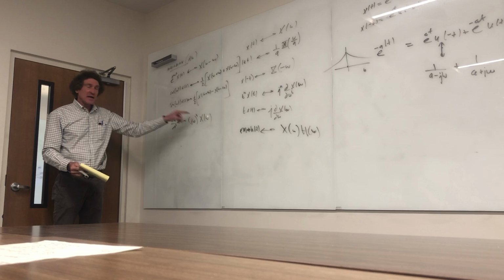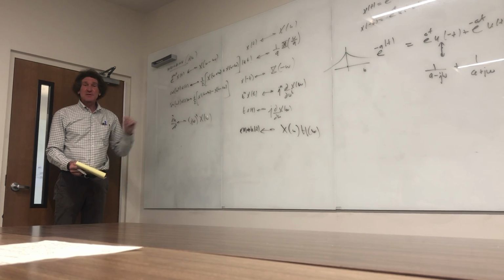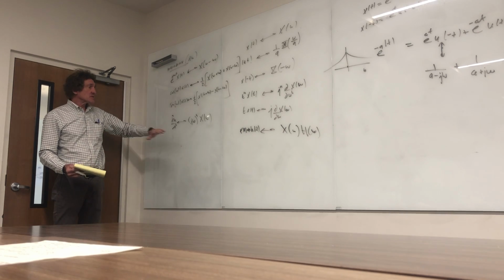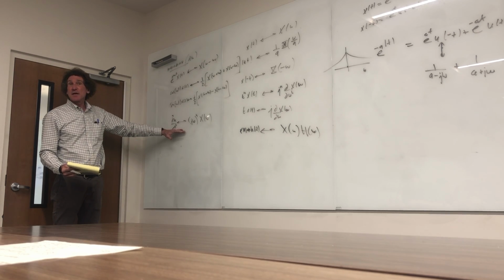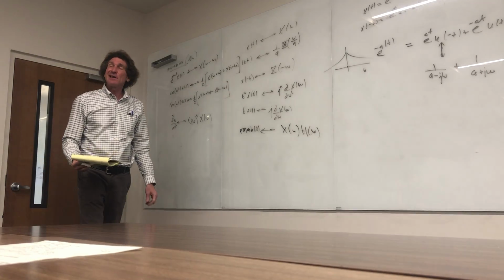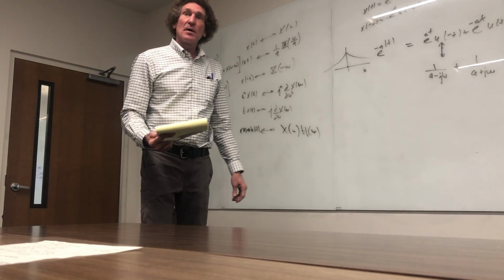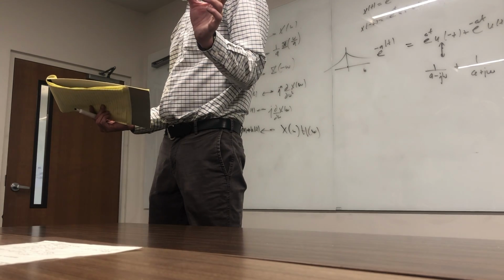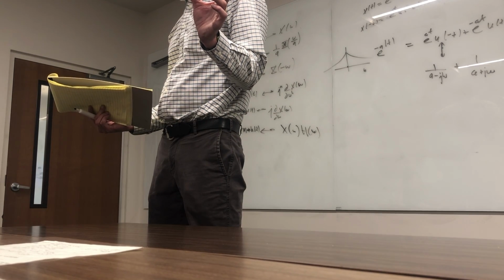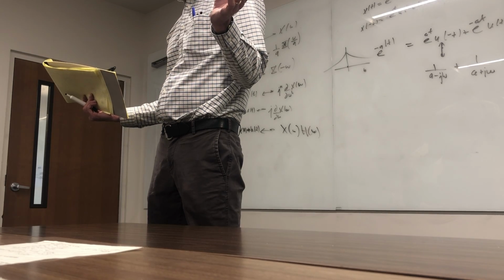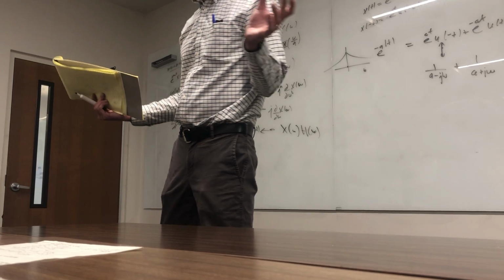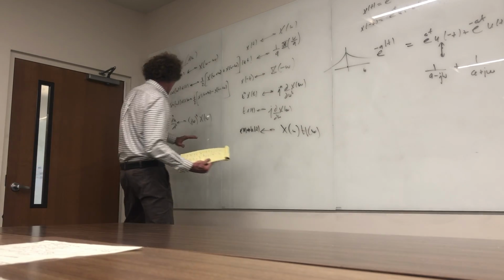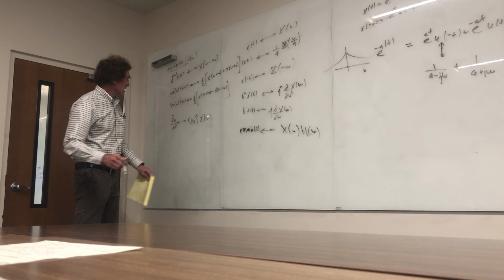Second derivative would be (j omega) squared times X of omega. Do y'all follow me in this, class? How many remember that? All right, this is key. And I'll tell you where you really use it. Think about voltages on inductors and capacitors. The voltage on an inductor is L di/dt, right? Well, that di/dt literally just pops a j omega out in front when you take the derivative, if i is sinusoidal or cosinusoidal. Please realize it has applications to solving circuit problems, and I'll have to show you that. Just remember that one.